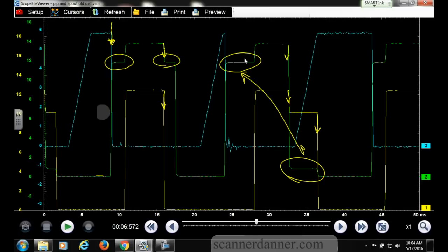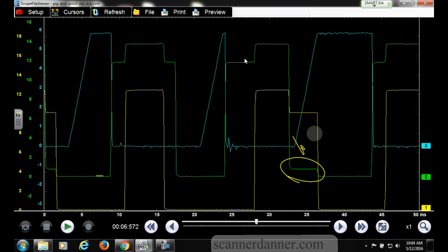So you said some new distributors can cause this? New distributors? Yes. This distributor that is in this vehicle is not very old. It's been done within the past year, so it's not an old distributor. I have seen these bad right out of the box. Granted, it might be a reman distributor, but I've been to garages. The one I'm talking about where I got my butt kicked was a newer distributor that was just replaced and had this issue.